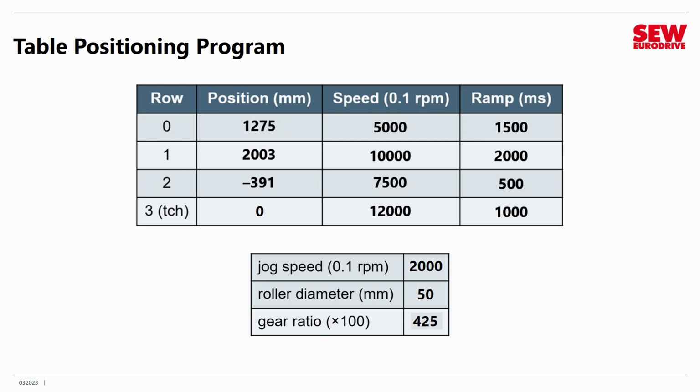Just so we're on the same page, I'd like you to use these values in the table. So set up the positioning table as shown. Notice I've put a specific value in the teach location. I've put a 0 there. There should definitely be a known value that's legitimate in there. Of course, later when you teach the application, this value will change, but at this stage, you need to at least have a position you could go to if you haven't done a teach operation yet.